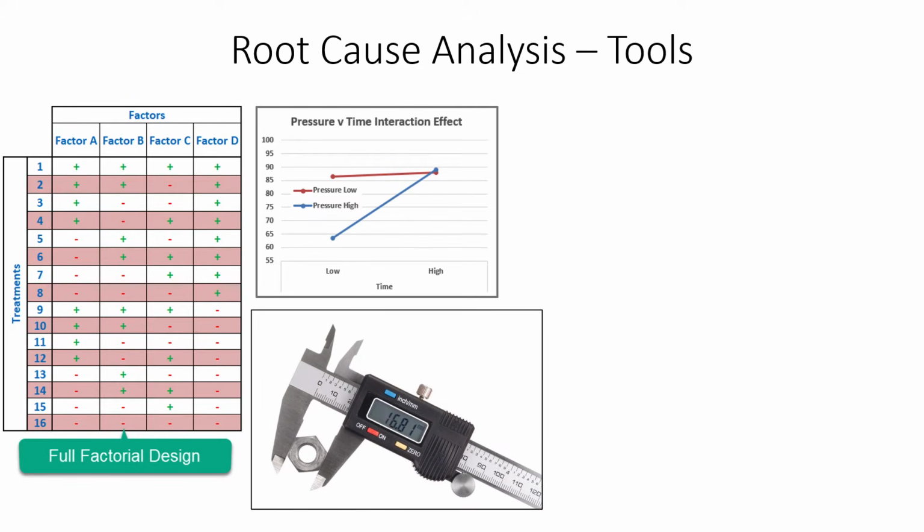Another aspect of really getting down to the root cause often involves measuring parts. So it's not uncommon, as part of the root cause analysis, to create this failure mode, measure it, and quantify it. This can obviously help lead to root cause, but it can also help with a risk assessment. Oftentimes during a risk assessment, we have to quantify how severe the failure mode is. And sometimes functional testing can give us some insight as to how bad the problem is. That testing can also give you insight as to how frequently the problem is occurring.